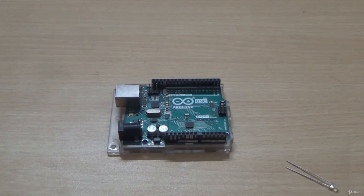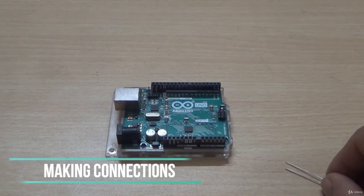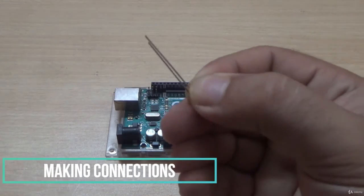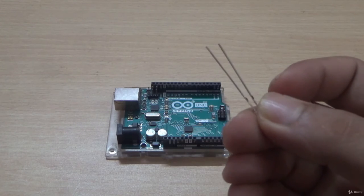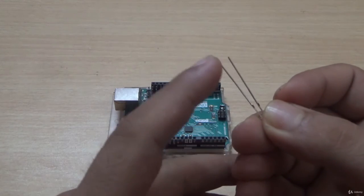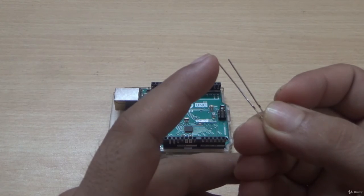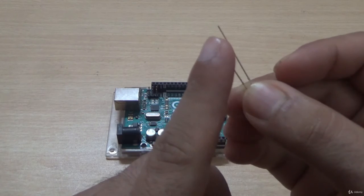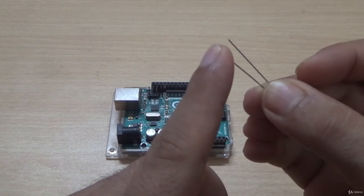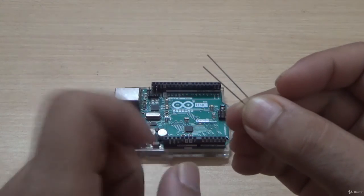Look what I have. I have Arduino Uno and this is a red color LED. Now this LED has two pins. The long one is anode. This should be connected to the positive terminal, and the short one, this pin is cathode. This should be connected to the negative or ground, and long should be connected to the positive.